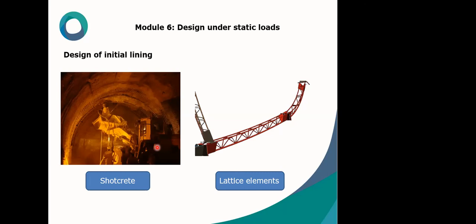The workability or efficiency duration for initial lining is less than 2 years. So the seismic loads are not considered in designing initial linings. On the other hand, there would be an obligation to construct final lining in its section of the tunnel before 2 years from the completion of the initial lining construction.